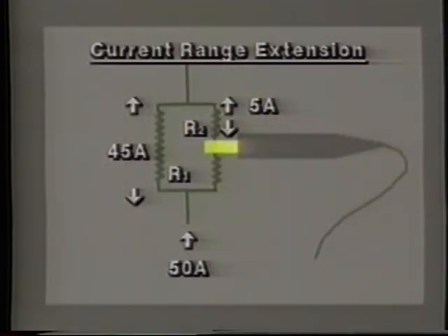You pay for cheating in other ways. In this case, I've introduced unpredictable parasitic elements into the measurement system that may become significant at higher frequencies. A second example: how can you measure a 50 amp signal with a 20 amp probe? Well, you could build a shunt pair with a 9x resistance ratio. Only a tenth of the current, 5 amps, will flow through the probe. Nice idea. Yes, but you have to know your resistances exactly, or we directly throw off the measurement, and the low-value resistors you probably need are usually not high-accuracy parts.